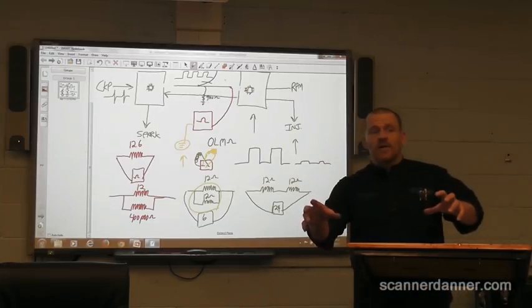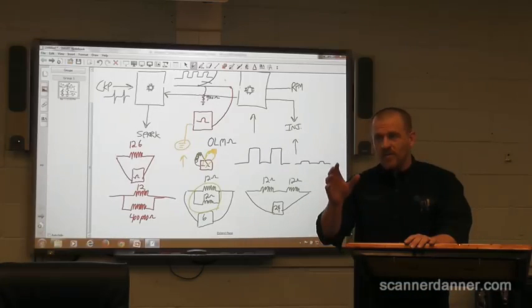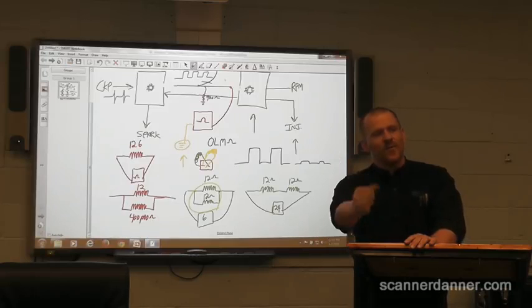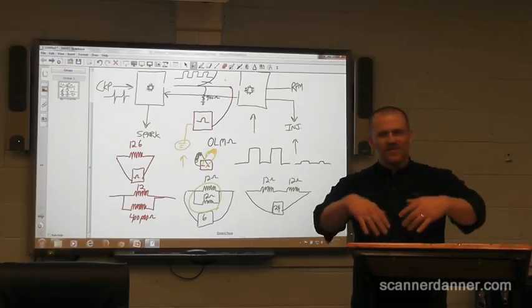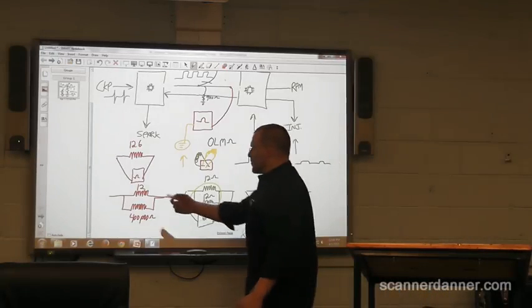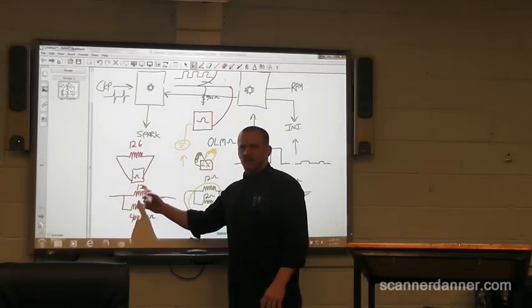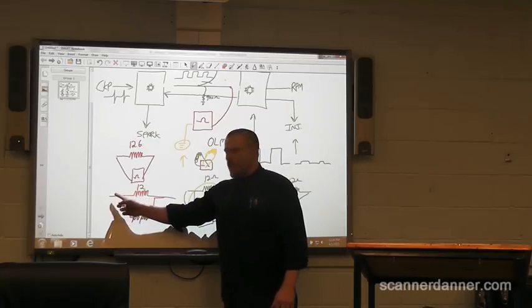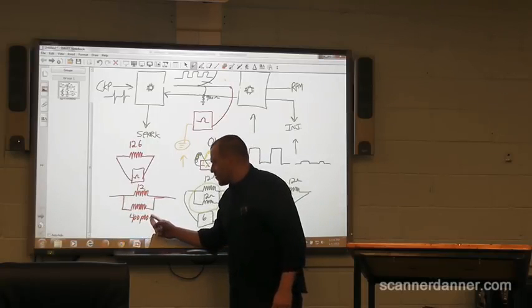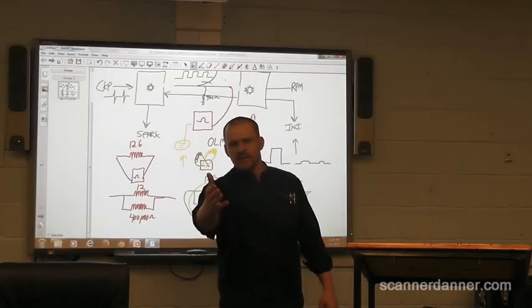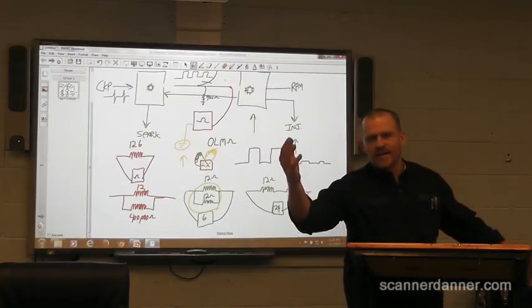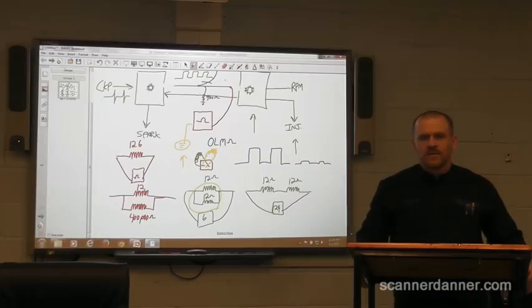There are some parallel laws. Hold on. Parallel laws. The total resistance will always be what? See how much you retained. Higher than or lower than the lowest resistor in the circuit? Always lower than the lowest resistance. There's some common sense to that. The reason I tell you right now that the number will be less than 12 is because we have an alternate path for current to flow. Even though it's a real high resistance path, total resistance would still be less than 12. What is it? A lot less than 12. 11.9, what? Is it? You're dividing 12 by that.